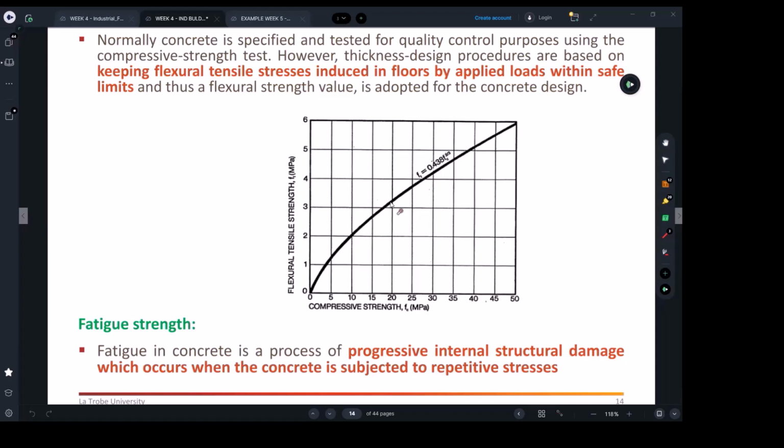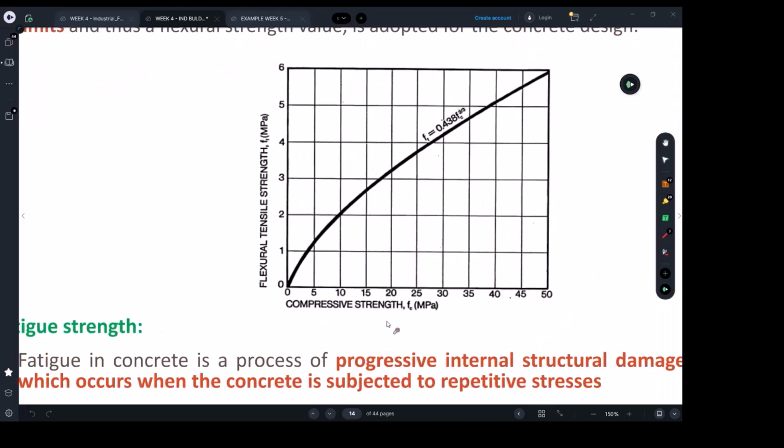However, that steel can also be used for flexure, because shrinkage will happen only during the process of hardening the concrete. Then as a permanent use, yes, the minimum steel we placed can be used for flexure. Now, sometimes that steel is enough, sometimes not. And there are charts like this, which will tell you what the maximum is that the gray concrete can take. And this chart shows you it's a function of the concrete strength.